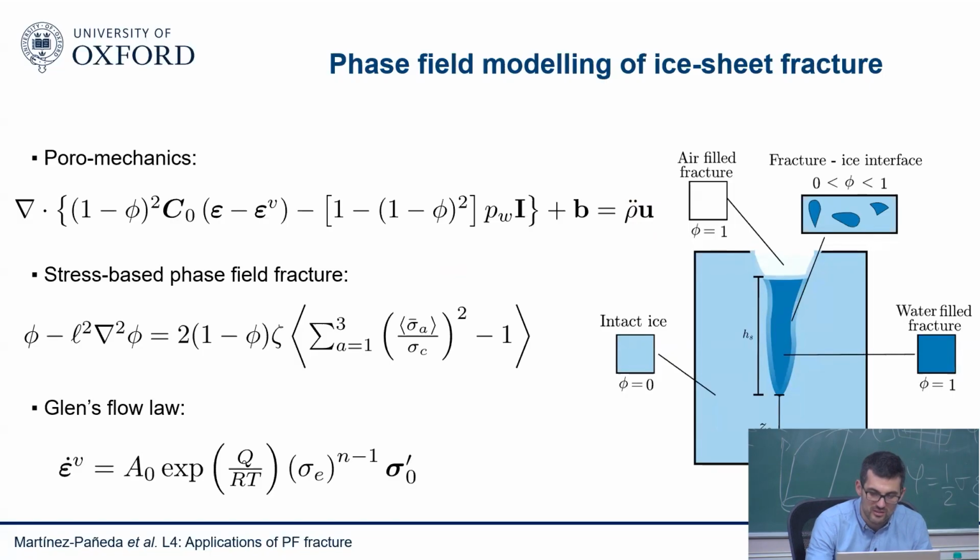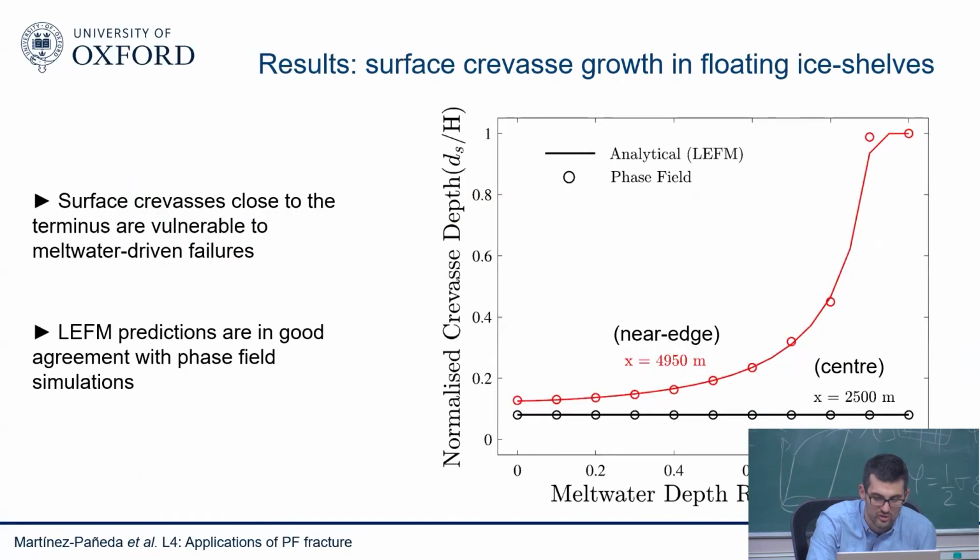And here the challenge is that if you think of a gravity load, think of a force displacement curve, you are somehow telling your component that your gravity load remains constant in time. You have a load that is being applied, but your material is losing stiffness. So somehow your gravity load has to go down, but you are at the same time telling that gravity load to remain constant. So it's a bit of a challenging problem from a convergence perspective.